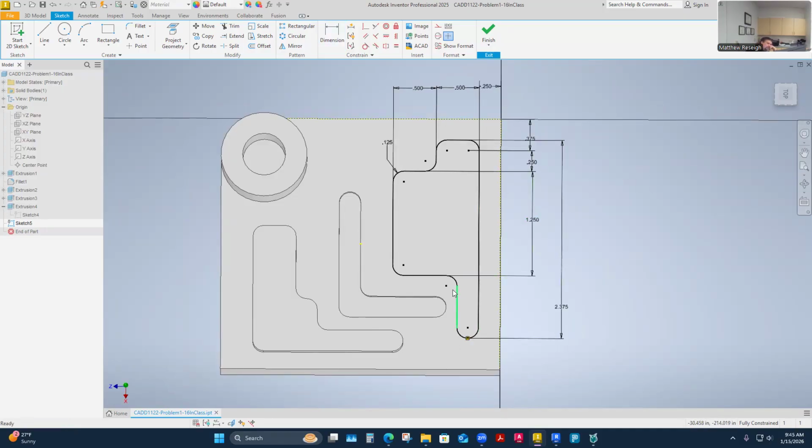It might not be how I would choose to constrain that myself. If I wasn't given the dimensions to work with originally, I might constrain it somewhat differently, but this will work. Or I might dimension it a little bit differently. I think it was Riley that pointed out to me that it is kind of annoying that some of the dimensions go from point to point, some go from line to point. And I agree with that. Usually I have a more systematic approach to dimensioning, like dimensioning to the outside edges all the way around and not to the centers of radiuses. So I can't say that I would choose these dimensions if it was something I was totally walking away from, but this will work for us.